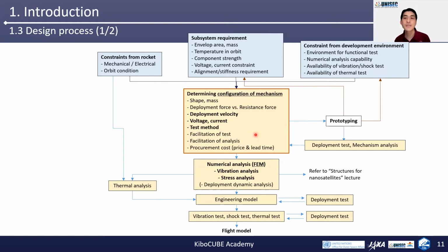Some tests require large facilities, such as large space and high ceiling with gravity compensation mechanisms. Some numerical analysis is very difficult to conduct, such as a geometrically nonlinear finite element method or a transient nonlinear dynamic analysis. You may need the participation of a specialist in numerical analysis. Thus, you have to consider your constraints from the development environment or resources you have. If the mechanism design does not facilitate verification, you will avoid the design.